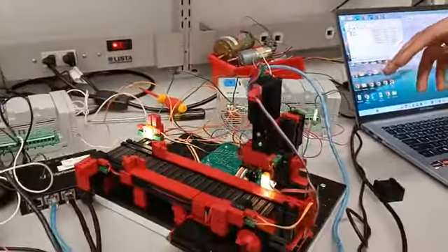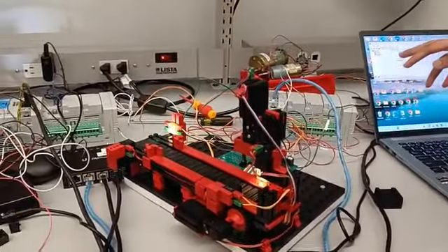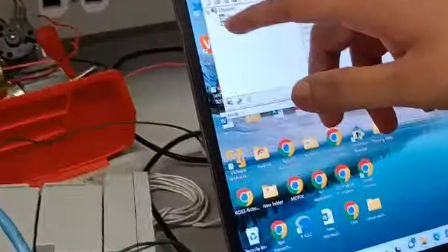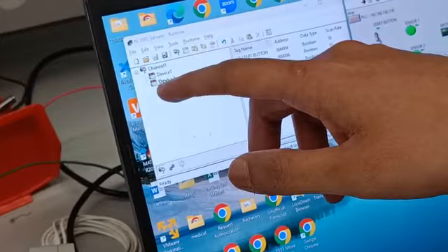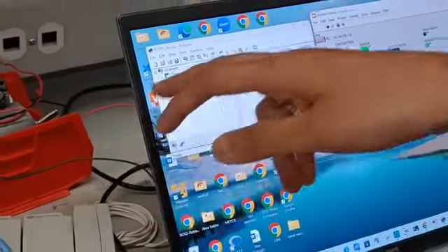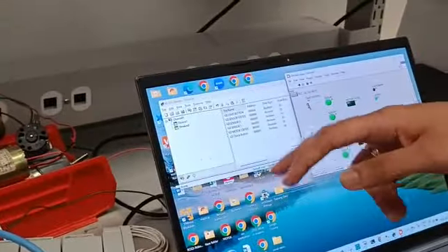So all three are in the same hub itself, and this is the NI OPC server. Over here, as you can see, I've generated two devices, device 1 and device 2, which are like PLC 1 and 2. I assigned an individual IP address for both of them for the communication part.